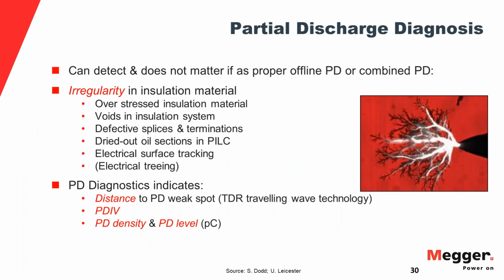And then the typical things that you see are irregularities in the insulation material, the classic voids, imperfections, protrusions. All of these things will cause partial discharge and electrical treeing at one point. At one point, water treeing will cause electrical treeing, even though those electrical trees are of a very different magnitude than real PD. So typically, it's very difficult, borderline impossible, to really catch those.